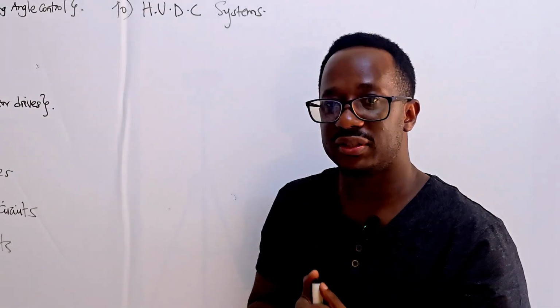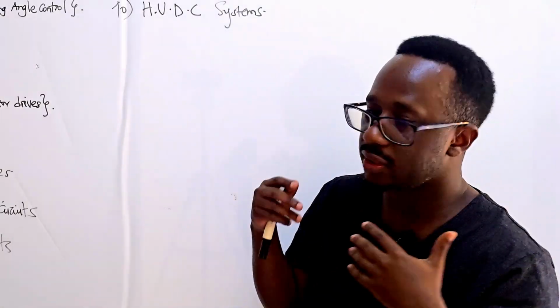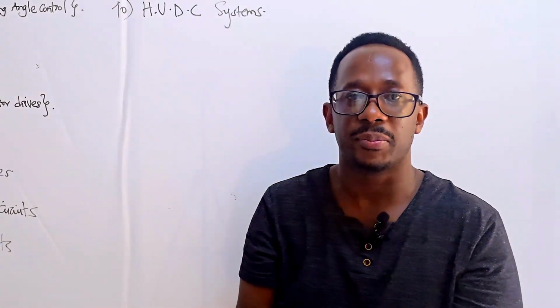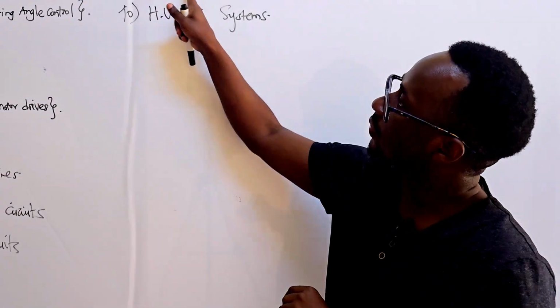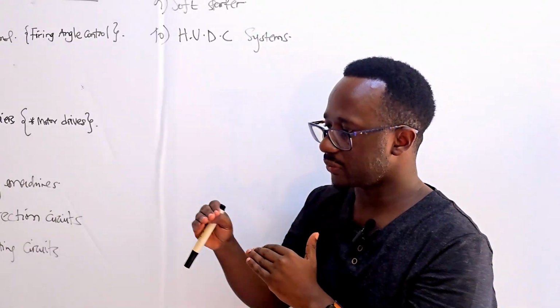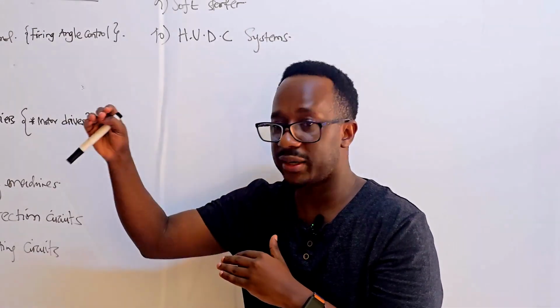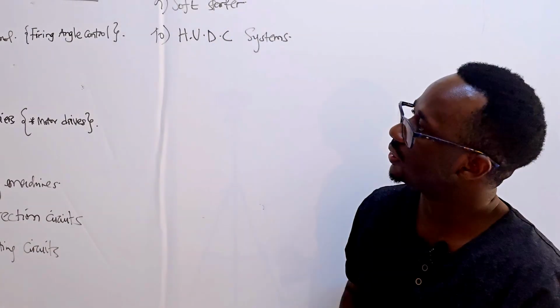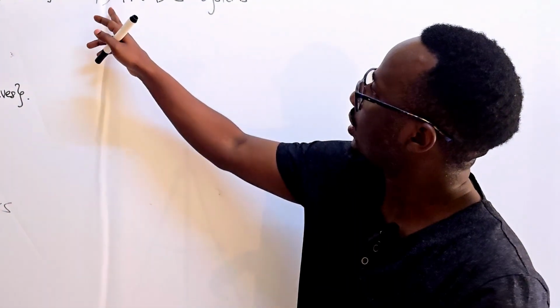So in order to avoid such issues, inrush currents and straining the power grid, we use soft starters. We control the turn-on voltage slowly. We ramp it up slowly. So an SCR or a thyristor could help you.